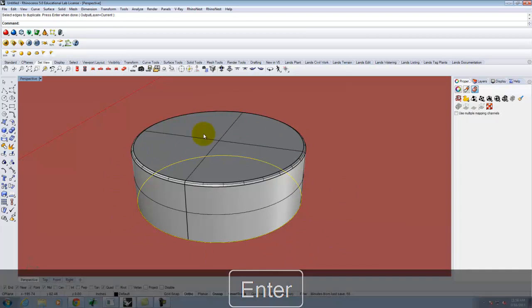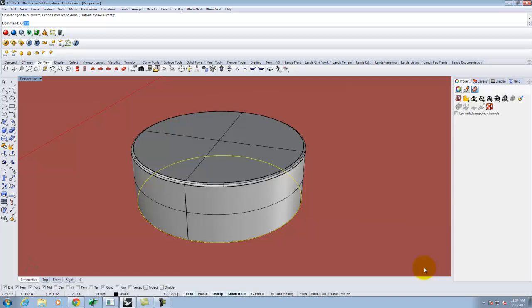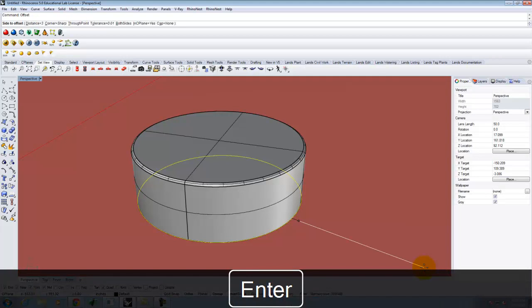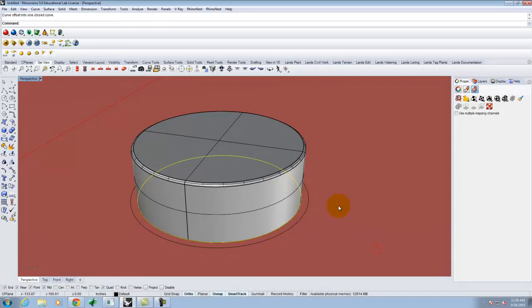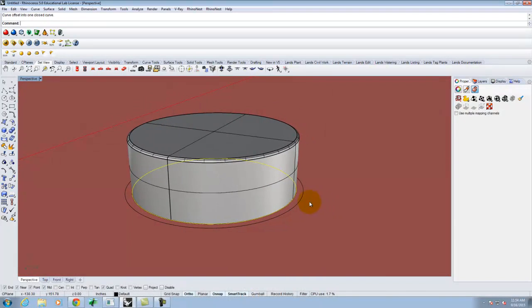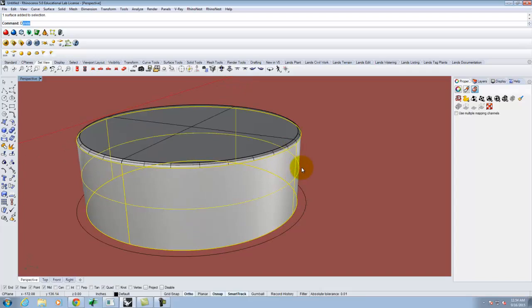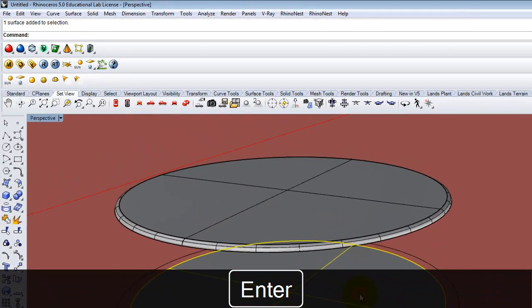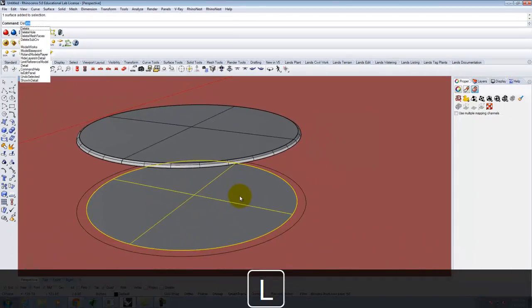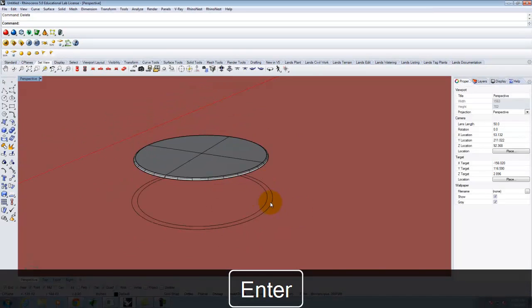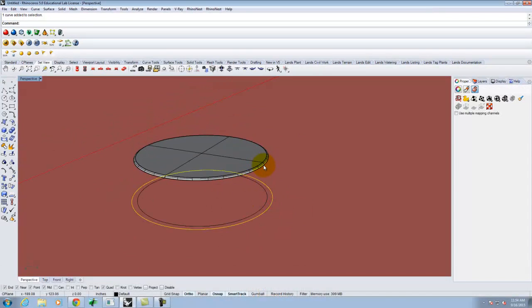And that gives me a curve here. I'm going to do an offset. And we'll offset the flare maybe of 3 inches or so of the tablecloth, something like that. And the last piece, I can actually delete this because we don't need it. Right, I just need this curve. The last piece is that I want to define a surface that goes relatively straight at the top and then flares out to that 3 inch.